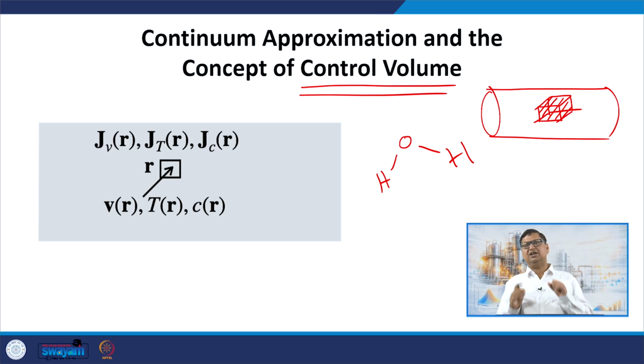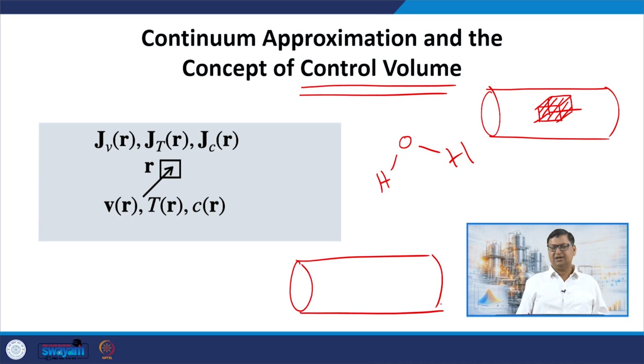And the way it is typically used is like the following. So, we no longer say that we have a volume necessarily, of course, it is used in derivation. What we say is, at any point in the fluid, I can define a velocity, and this velocity is not of a fluid molecule, but it is the velocity of all the molecules in a control volume I can draw around this particular point, and some kind of an average of that, right.